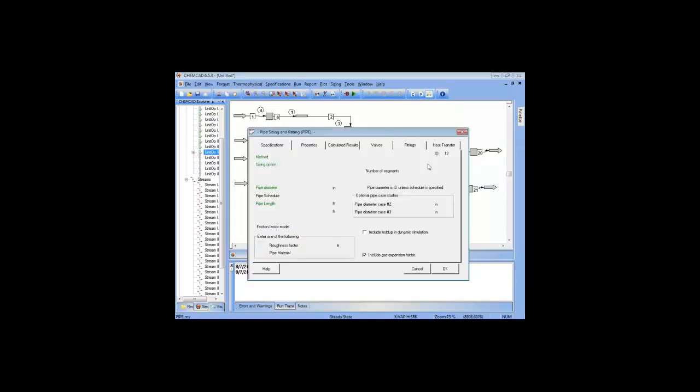That actually means we have two different small flow networks. We have this one, which we have set, and we're not going to adjust or change at all at this point. And we have this one. So we have one that mixes, and we have one that divides flow. First, we have to make sure our pipes are in flow scaling mode, sizing option 5. That is 6 and 750 feet. We can leave that. That's fine.